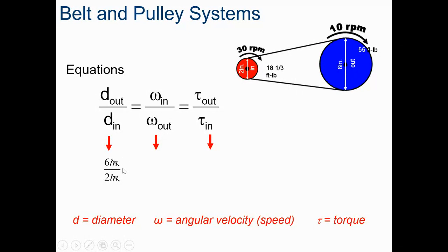So there we go. And if we look at the ratio between the angular speeds, now again, this is the same formula as we used with the gears, so it's still going to be input over output for the angular speed, just like it was with the gears. It's going to be input, which is 30 RPM, over the output, which is 10 RPM. So we're going to get 30/10, and we notice ratio is still 3:1, 3:1.